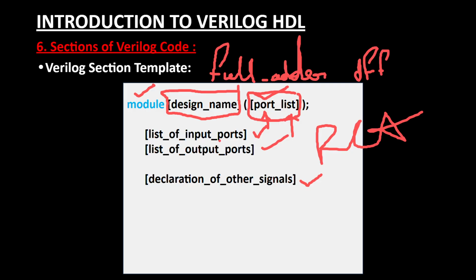Only the signals which are going to appear to the outside environment should be declared as input and output based on their functionalities. The internal signals which are going to transfer from one module to another module, we shouldn't declare as input and output, because if we take those as inputs and outputs, we would have to create a pin while designing.